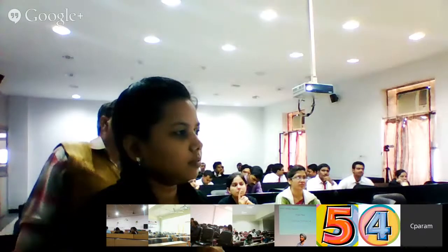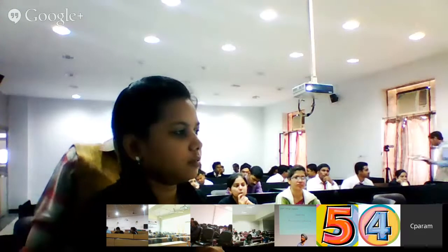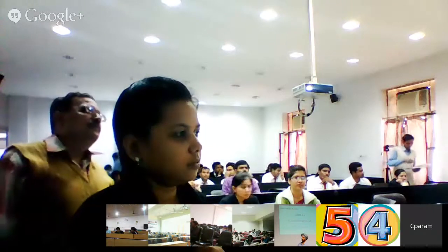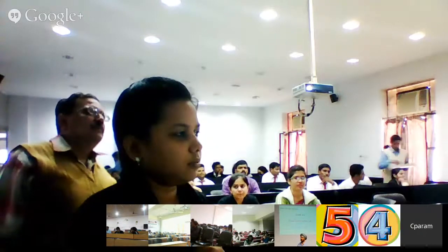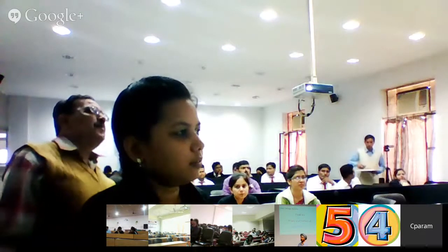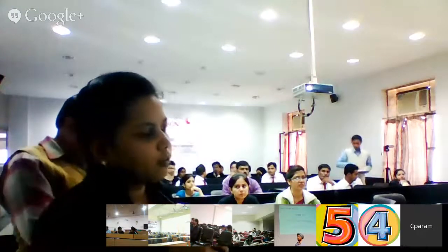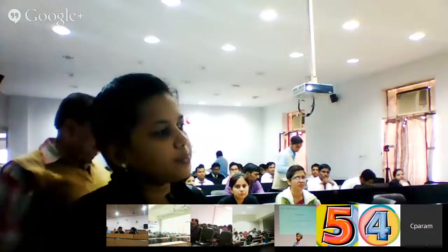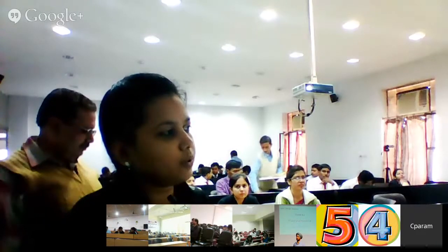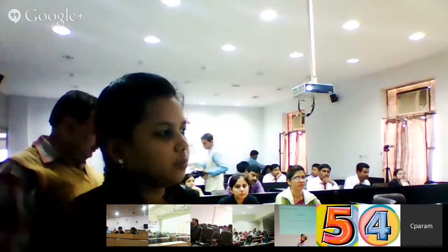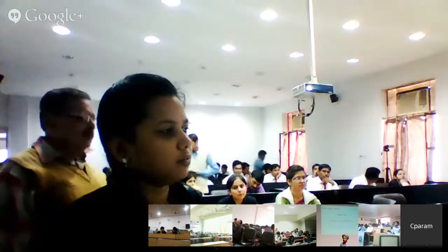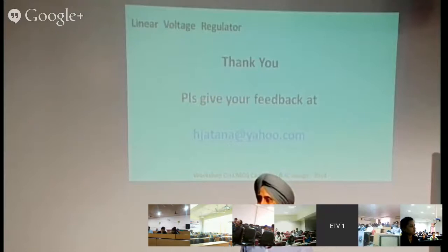Now your question is on PSpice. You should have the model parameters, which you will get from the companies; they have the exact model parameters. Otherwise, in PSpice, those parameters are not exact. For each technology, you should get the model parameters.